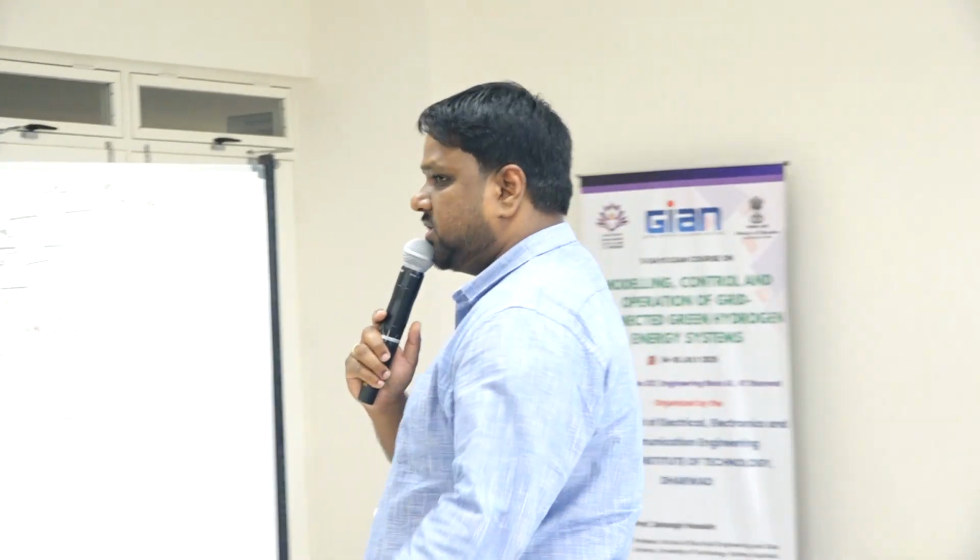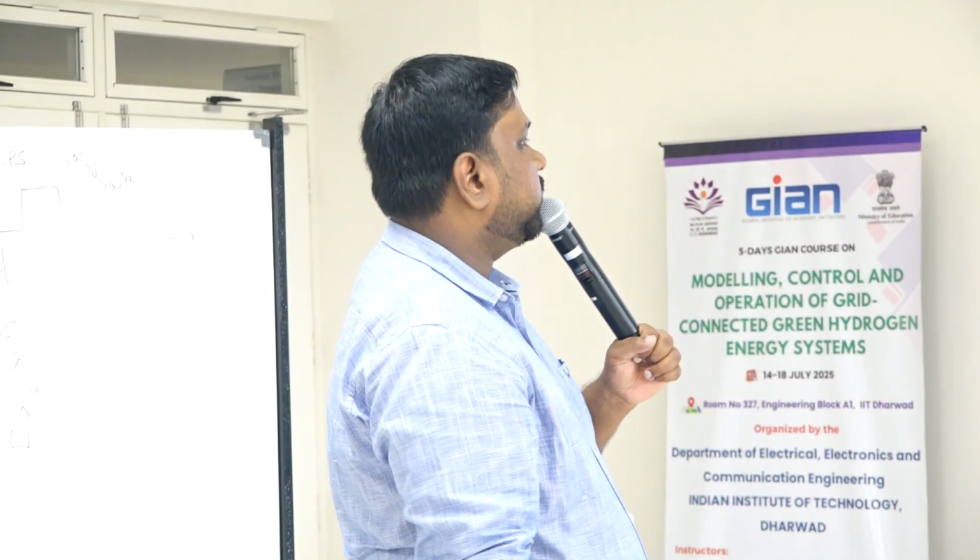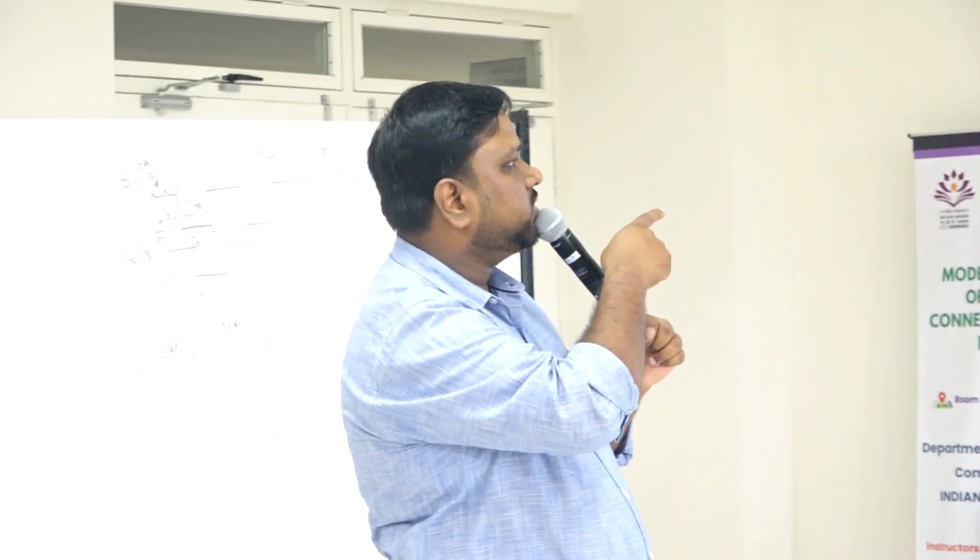So now we will do a simple simulation, and the rest you can do at your home. We will see the tracking performance. We will give a step change to the reference voltage and see how the measured voltage is tracking: how much overshoot, how much settling time, all we track. For that, we are replacing the V0 reference with a controlled step change. You can find it as a stair generator.